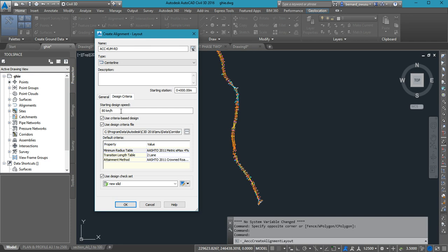The design speed. Although we are saying Accra-Kumasi, what we have there is 80. Let's use 60 for now. It's just an example. I'm saying 60 because this road actually is not Accra-Kumasi. It is a regional road, and it's going through settlement and mountainous terrain. So we have to use a lower speed. Let's assume that our design speed is 60. Are we okay?